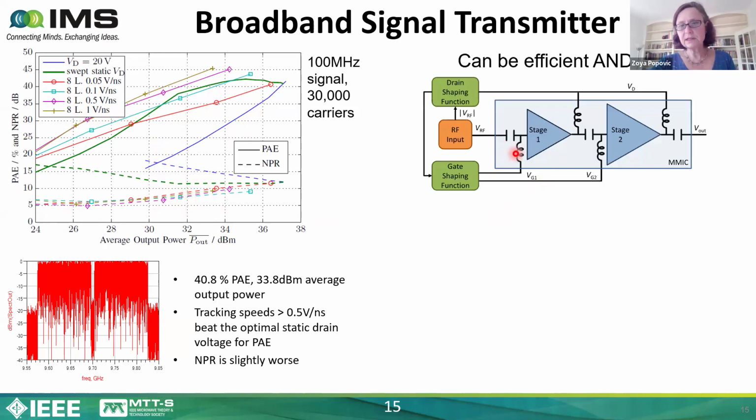For example, you can decide to control the gate. People do analog linearization, but more dominant today is digital pre-distortion. That's digital linearization. I'm a believer that you should maybe try to do both, do something at the front end so that you help the digital back end. And so what we did is control, for example, the gate voltage, because what that does is control that huge gain variation.